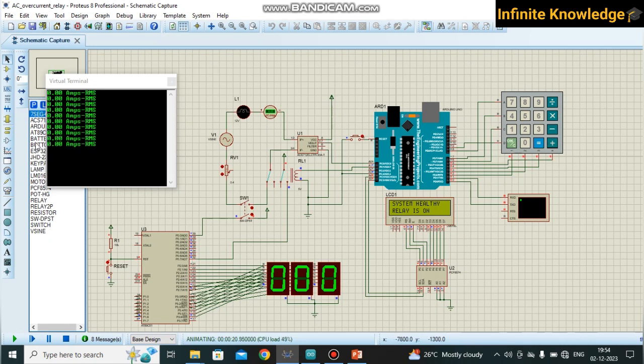This is how the circuit starts, and it's a circuit breaker. Whenever I start the circuit, it calculates how much time to trip. It's taking 5.28 ampere, and you can see here it's serial based communication, and your system is healthy. Your overcurrent is 99 and the actual current is 5.28, so it's very low.